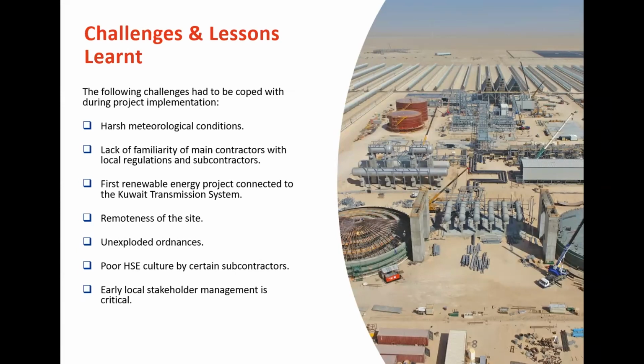of the plant. It required, for instance, using a very specific type of wind turbine that was designed with this kind of high dust, high temperature kit in it to make sure that the nacelle's cooling system was able to operate at high temperatures and without impacting significantly the power generation of the wind turbines. This is just an example.